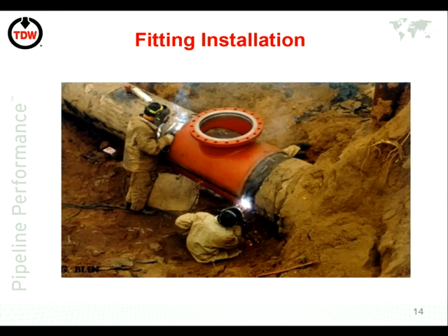So before you take this out, when you are accounting for this kind of project and you have external coating on the pipeline, that has to be cleaned off. It doesn't show it very well here, but that pipeline has been thoroughly cleaned. You can just see the coating there. So that's the coating which will have been removed to allow the welding.